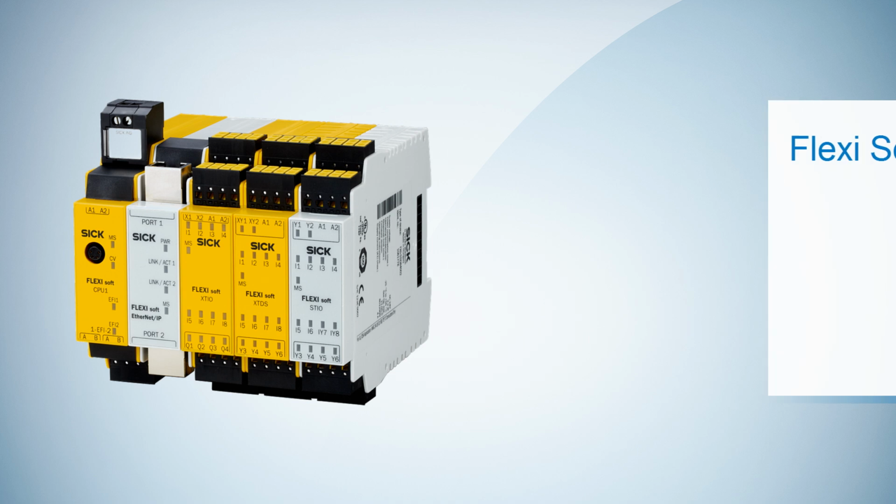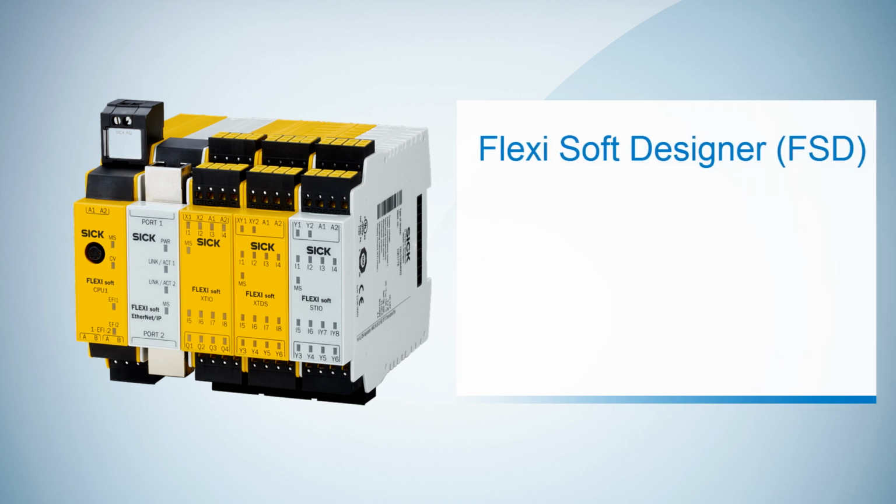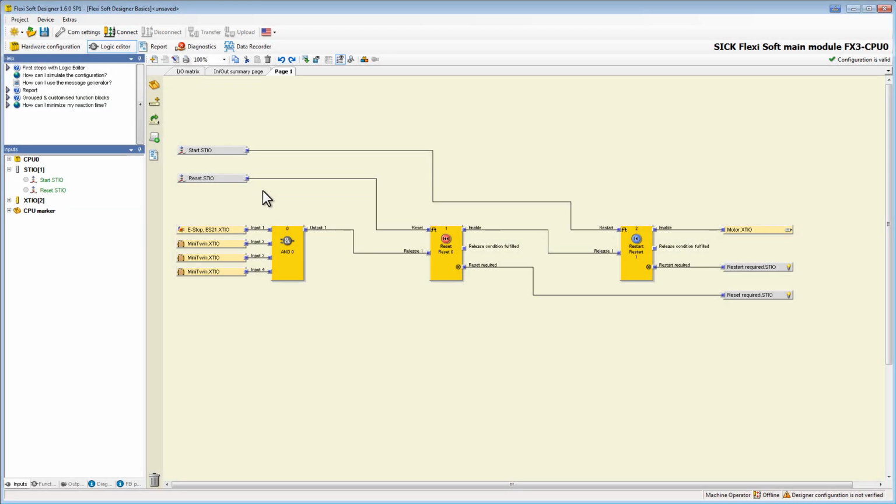Hello! In this video I will explain the use and functionality of CPU markers and jump addresses. Jump addresses are used to structure your logic. To put it simply, you could also see a jump address as a wire with a name. Wherever you have long wires or want to jump to another page, just use jump addresses to give your logic a better structure.